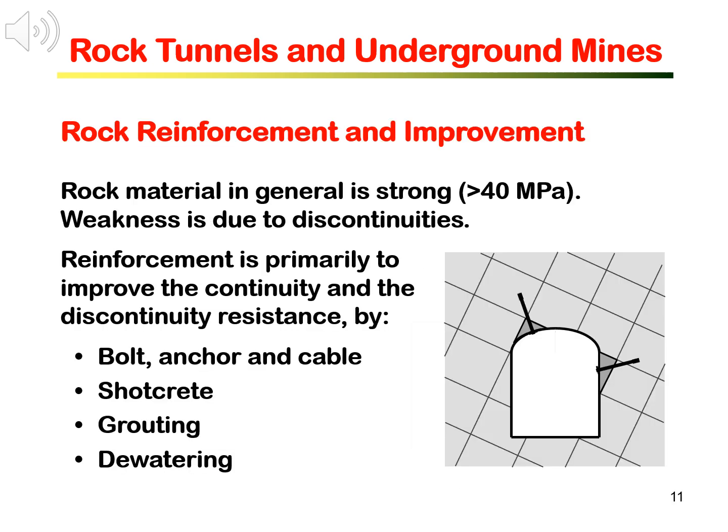Although we often use the term underground rock excavation for tunnels in mine development, actually, in underground development, particularly underground construction, maintaining stability of the excavated opening is often more important in engineering. Rock tunnels and caverns stability are generally maintained through rock reinforcement and rock support.